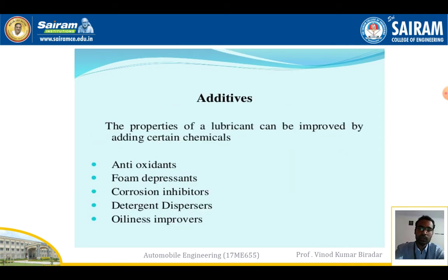What are additives? The properties of a lubricant can be improved by adding certain chemicals. Additives are substances added to the lubricant oil to improve its quality, efficiency, or properties. Additives may be antioxidants, foam depressants, corrosion inhibitors, detergents, and oiliness improvers. These are some additives.